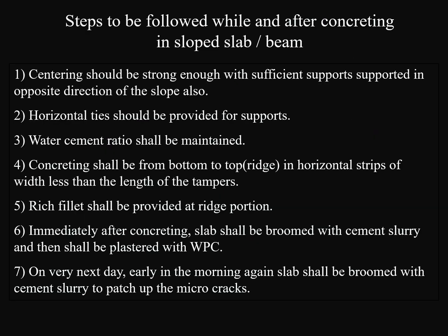Steps to be followed while and after concreting in sloped slab or beam. Centering should be strong enough with sufficient support, supported in opposite directions of the slope also. Horizontal ties should be provided for supports. Water cement ratio shall be maintained as recommended by the designer. Concreting shall be from the bottom towards the top, that is towards ridge, in horizontal strips of slab, width less than the length of the tampers.